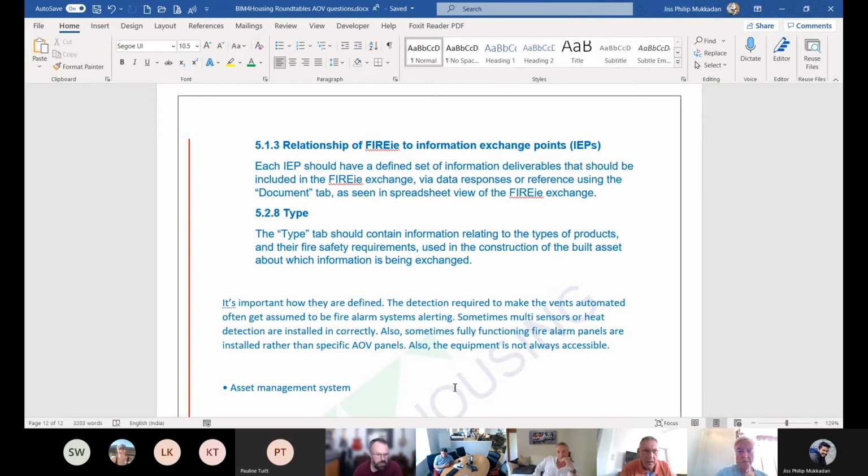On smoke control, something that comes at us quite a lot is about control equipment. We often want something that will actuate lifts and door releases, and if you don't get the right kind of control system, you can't do that. I've had quite a few at the last minute that say, oh, can you just sign this disclaimer? And the answer is no, because I'm not going to sign off a control system that's been put in under a different standard to BS 5839 because it was cheaper, without me being involved in the decision in the first place.